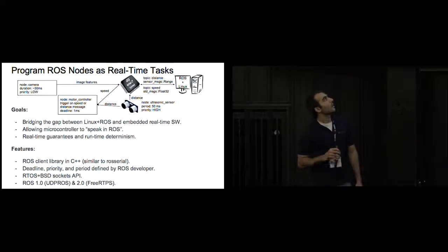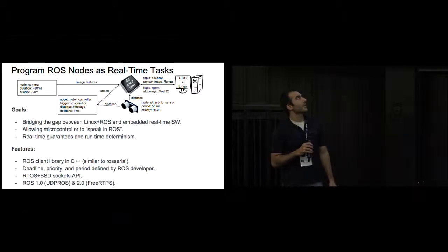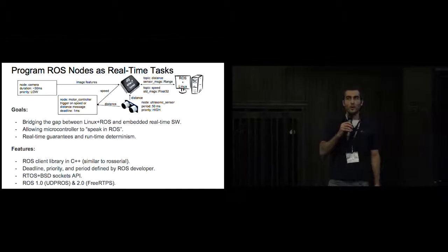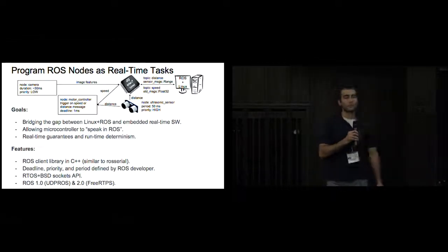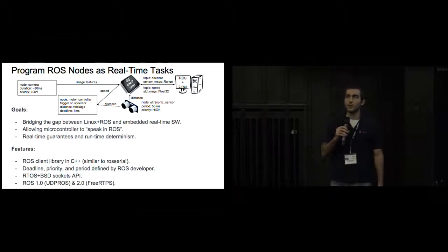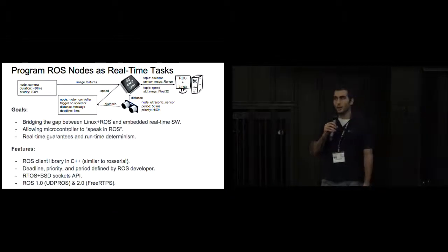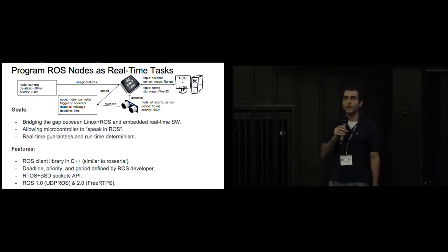So here's the real-time ROS framework for embedded systems. It's basically for small embedded systems such as the STM32 F4 Discovery, which I tested the framework with. The framework was tested with FreeRTOS, and we can have multiple software components in the system that act concurrently. For instance, a camera node, like you can see, and a motor controller at the same time.